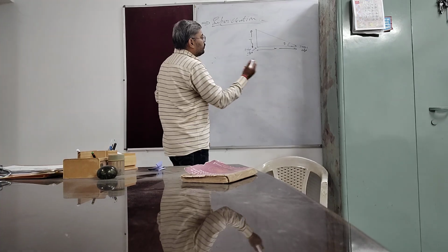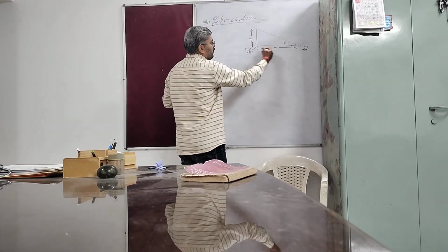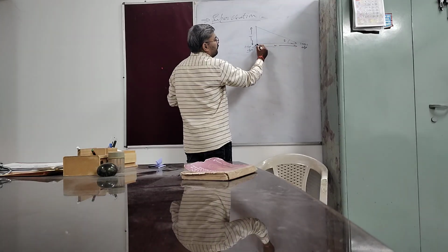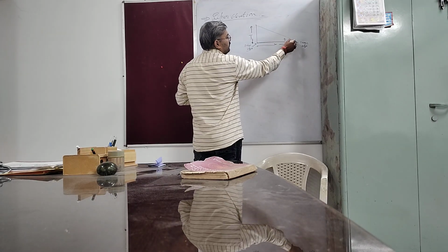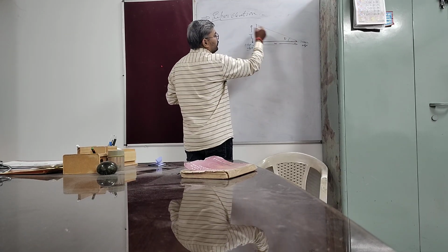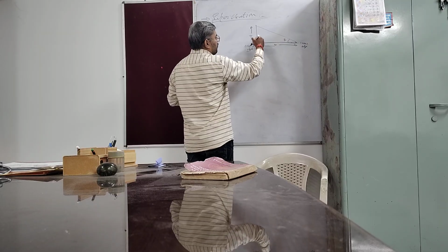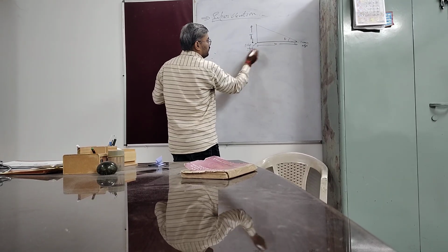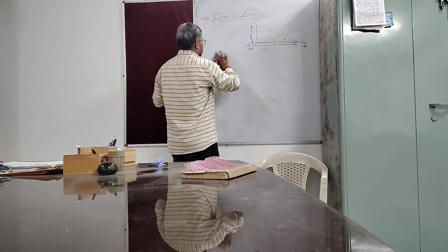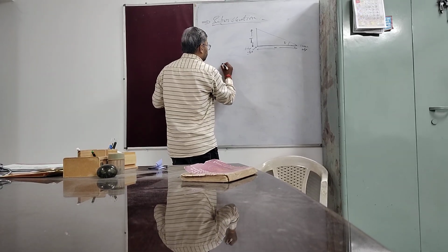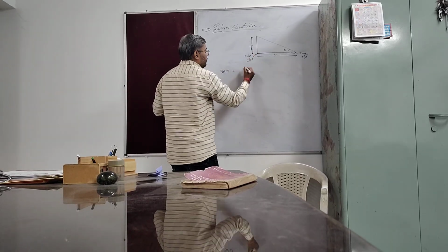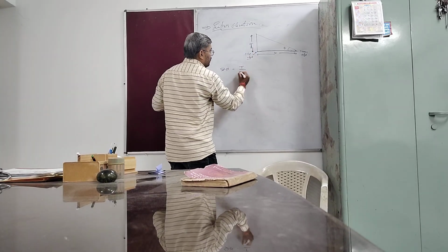At first, what is super elevation? We have to introduce this super elevation on a pavement surface. When the width of the pavement is W, then implementing a super elevation on the outer edge, the rising of the outer edge, is thickness T. So according to the sin theta rule, sin theta is equal to perpendicular upon base, that is T upon W.